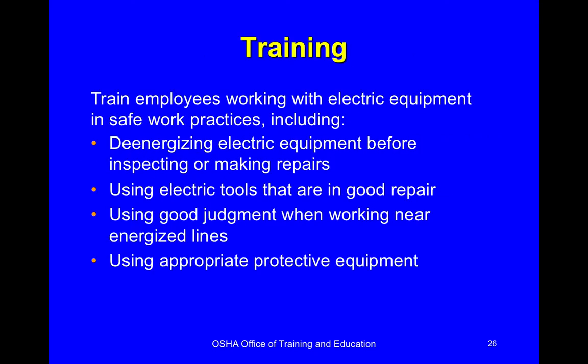Whenever you're on the job dealing with electricity, you do have to have training if you're going to be working with electrical equipment or around it. This is going to be looking at how to de-energize equipment before you look at it or make any sort of repairs, what type of tools you're using, making sure stuff is in good shape, and using your best judgment. Stop, think, what is the potential problem when you're working around electrical equipment? And if it's going to be required in your situation, what PPE do you need to wear and when do you need to wear it? How do you use it?